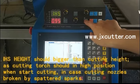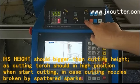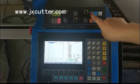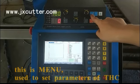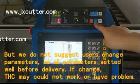IHS height should be bigger than cutting height, as the cutting torch should be in a high position when starting cutting, in case the cutting nozzle is broken by spattered sparks. This is the menu used to set parameters of THC. But we do not suggest users change parameters, as all parameters are set well before delivery. If changed, THC may not work or have problems.